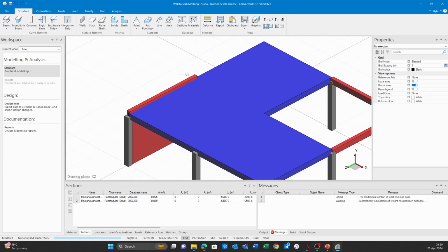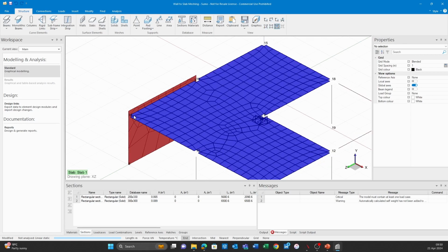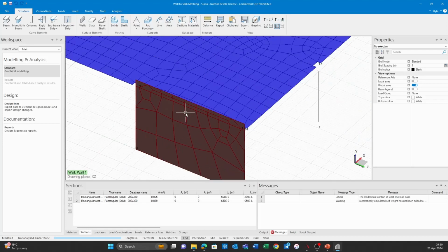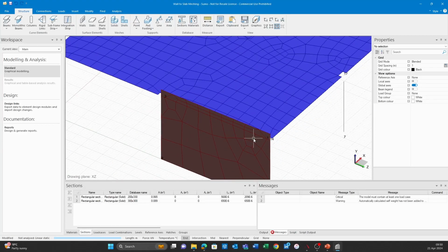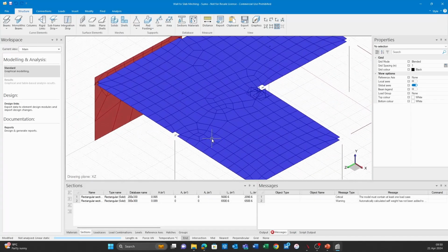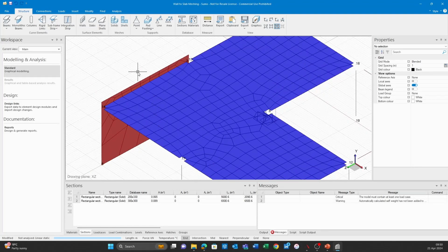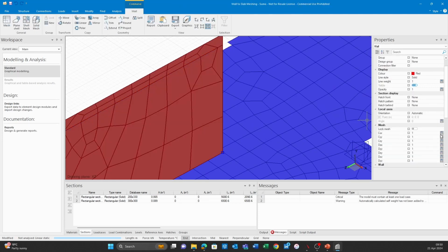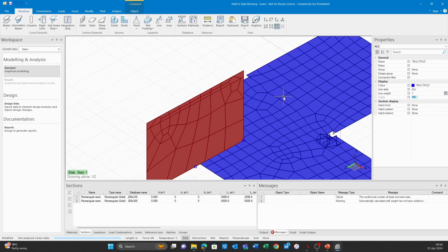Now, when you mesh, you're going to have some problems. If I go to my discretized model view, although it looks neat, we'll most likely pick up some problems because of what's happening with the meshing up here. Some of the shell elements can have a zero length, etc. As you can see here, at the moment this mesh size is 1 meter.